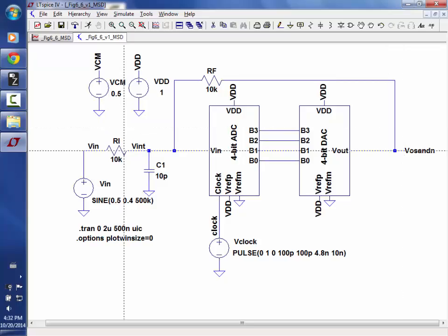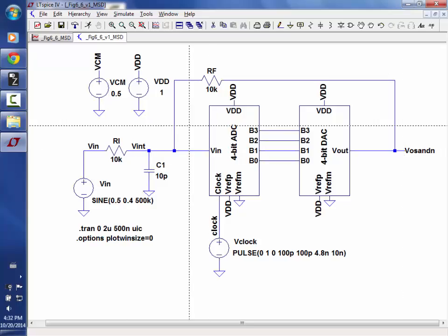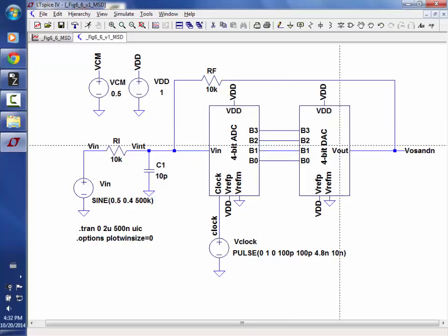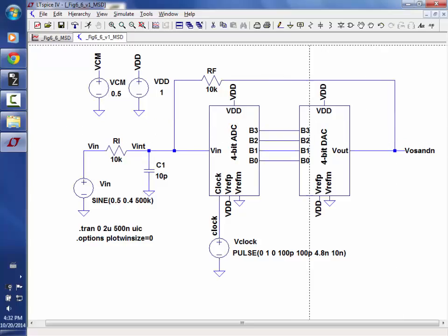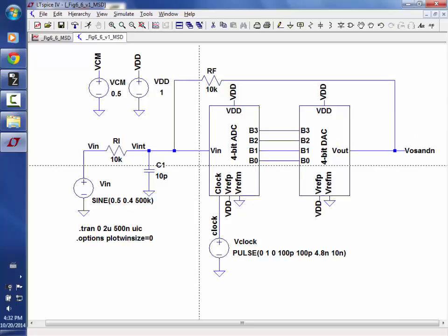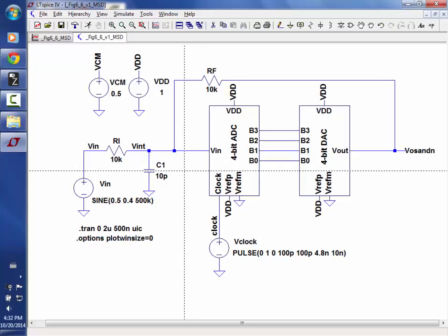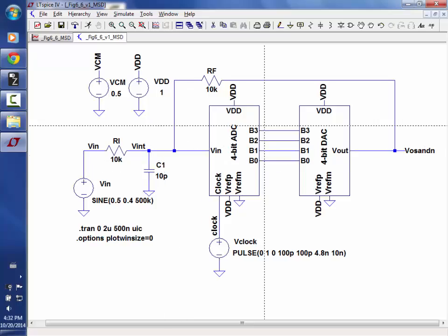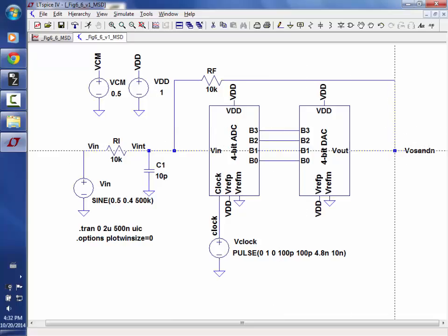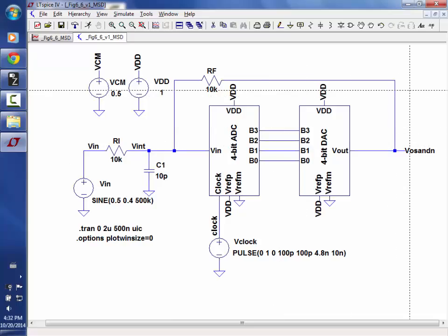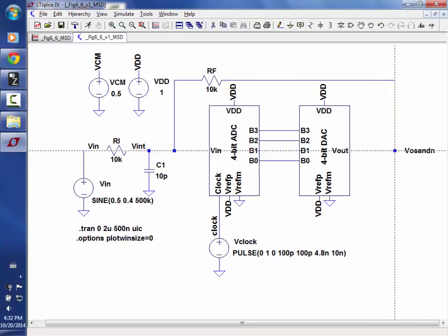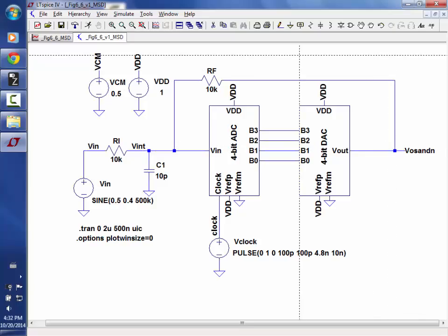Okay, so let's look at it again. If this signal goes up, this code goes up, this voltage goes up, and we get positive feedback. So the way I've got this working, it's not going to work. Anybody understand or not understand? Okay, so if this goes high, would everybody agree this code goes high? Would everybody agree this voltage then goes high? Everybody agrees I can't feed this voltage here, which is analog, to a digital inverter. That's wrong.